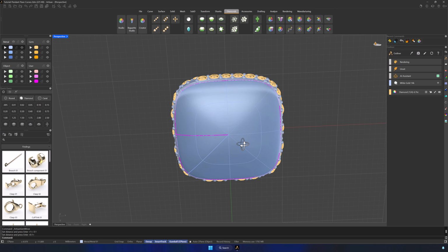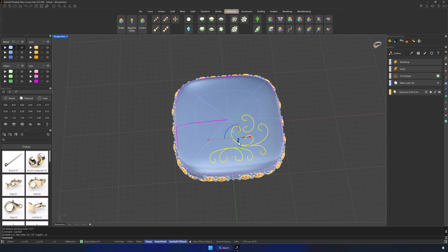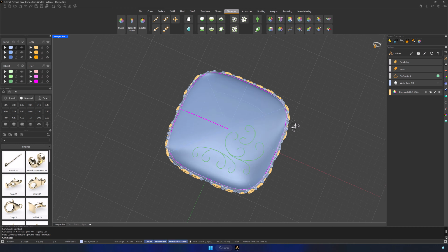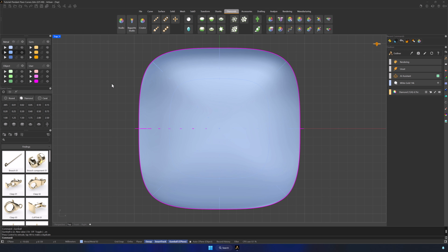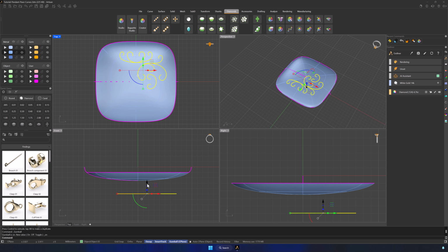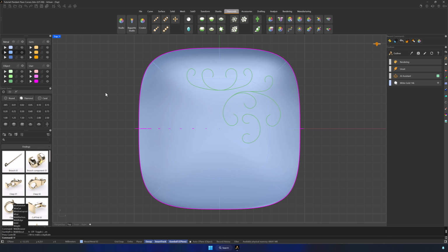Next, show the bottom surface and the curves. Hide the rest of the model for better focus. Move the curves inward and scale them to align the 2 points in the center. Use the Project command to project the curves onto the surface.